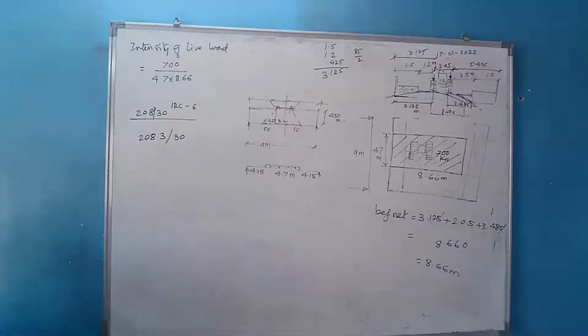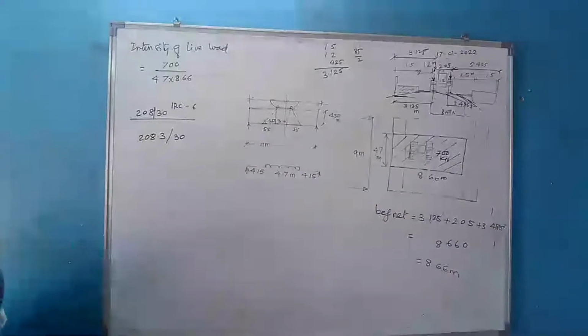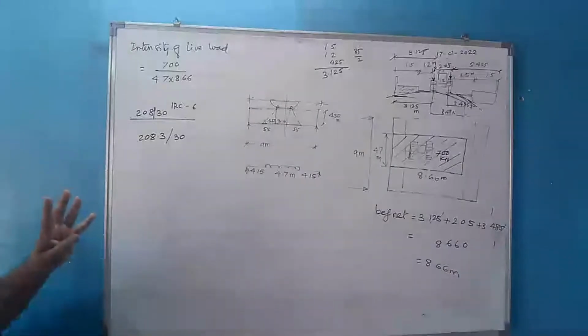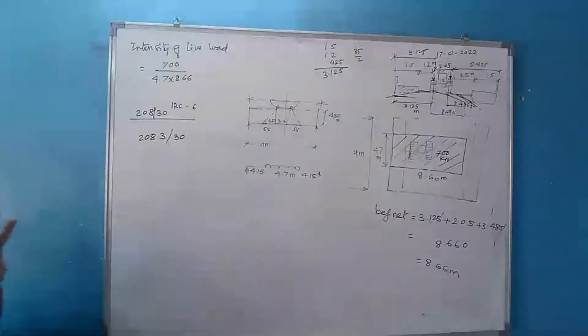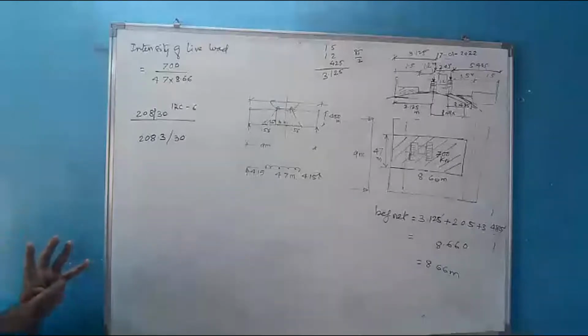So ours is reinforced concrete. Rather than reinforced concrete, we are using pre-stressed concrete, so it is equally applicable there. Reinforced concrete or pre-stressed concrete. So for a pre-stressed concrete deck slab bridge, for IRC class A tracked vehicle, there are three things: tracked vehicle, IRC class A, pre-stressed concrete, and the span. The span is 9 meter. These are the factors on which this impact fraction depends. So how much should we take? Will someone please suggest?